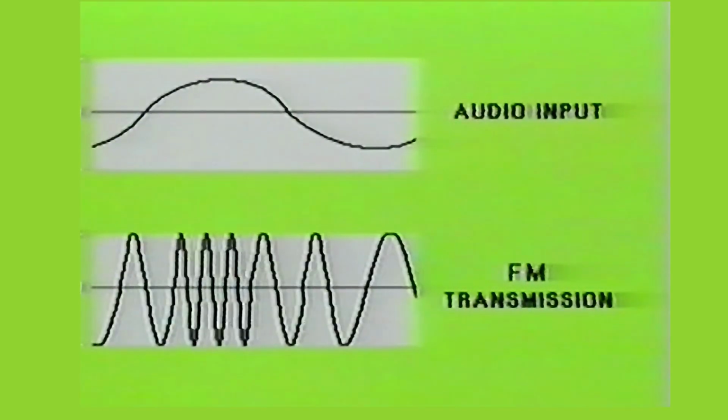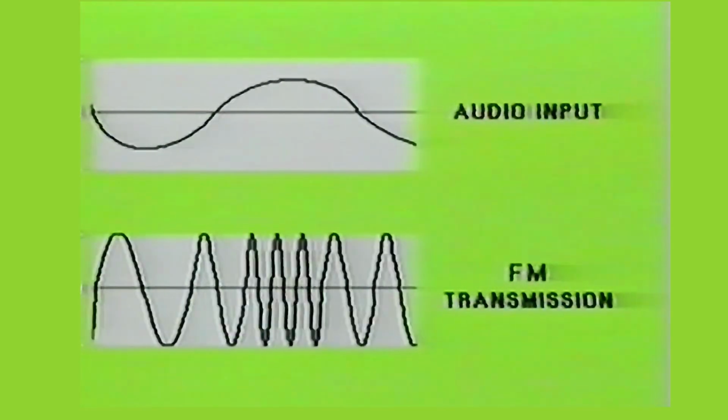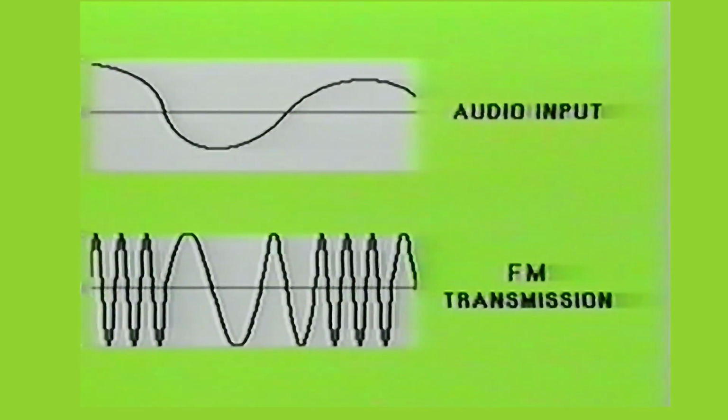The band set aside for FM broadcast stations is located in the VHF range of frequencies. It is placed in between television channels 6 and 7. This band extends from 88 MHz to 108 MHz. This band of frequencies is further divided into channels which are 200 kHz wide.